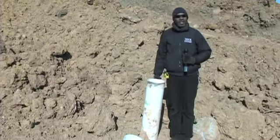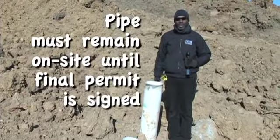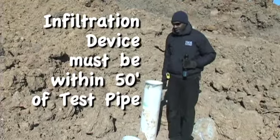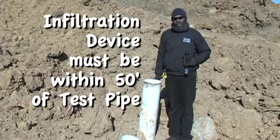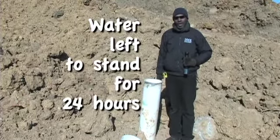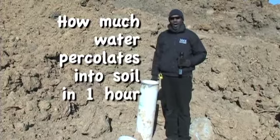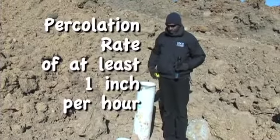This pipe has to remain on site until such time that the stormwater device is built so that they can put the infiltration facility within 50 feet of this test hole. And generally what's done for the test is the pipe is set in the ground and then it's filled up with water and allowed to stand for 24 hours. And then they come back and pour more water into the perk site and then test how long it takes for water to infiltrate 1 inch in an hour.